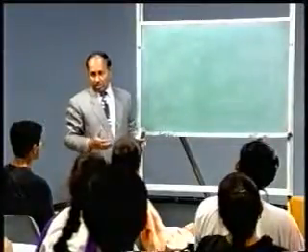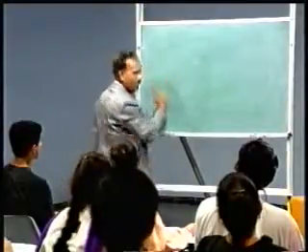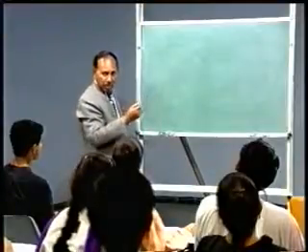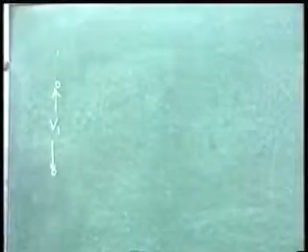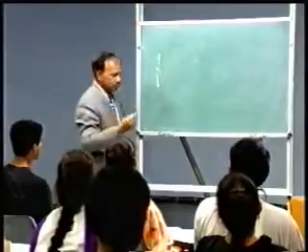Now let us refer to the phasor diagram of the transformer which you have drawn. From the phasor diagram, we try to draw the equivalent circuit. On the primary side of the transformer, you had applied a voltage V1. On the primary you have the voltage drops I1R1 and I1X1.